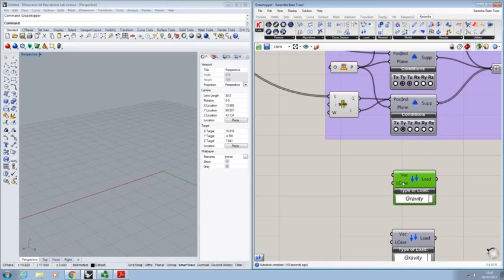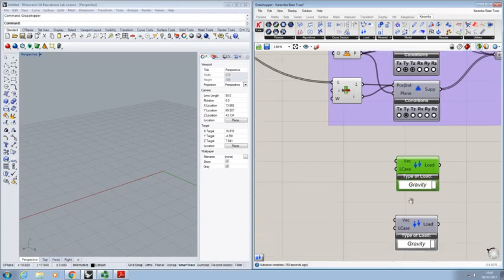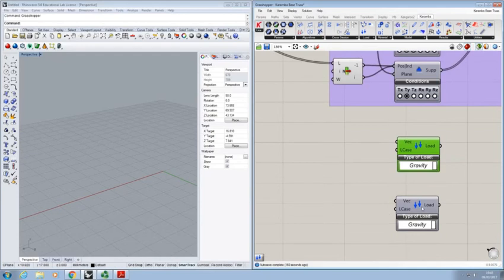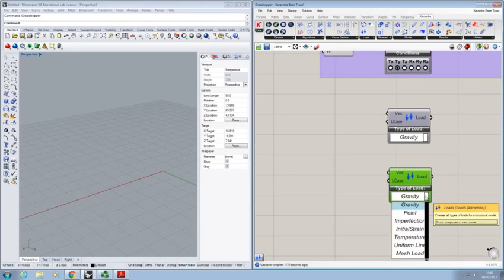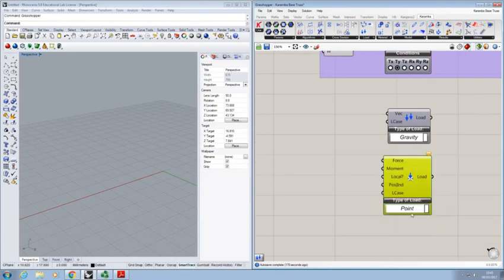And then the load case, if you hover over that, the load case is 0. So you can set up different load cases and call them different things. In this case, we're just going to have load case 0 and load case 1. So the second type of load we're going to have, as I said, is a point load. So from a drop-down menu in the second component, just choose point, and the component will change into one where you need to receive a lot more input.